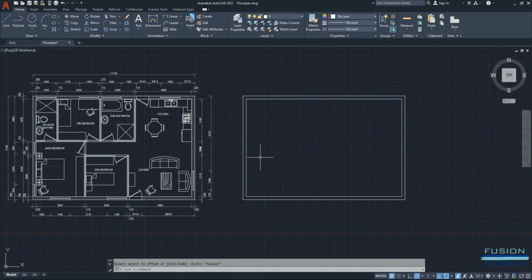Next we'll go ahead and draw our interior walls. To get started, I'm going to use the rectangle, and the first interior wall, I'll start from the top left hand corner, go to the end point, drag my cursor away so that I see an extension, and I'll type in 1500, press enter. Now I move my rectangle down and that length will be 110. That is actually the thickness of the wall. Then I can press tab and type in 3070 and enter.